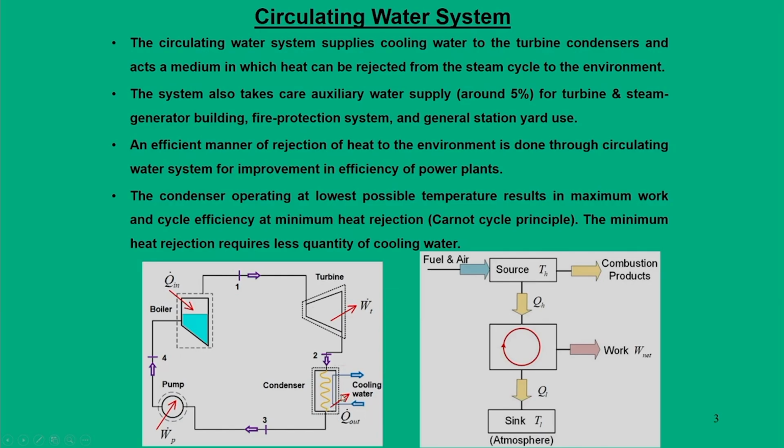Heat rejection is a must, because based on the Carnot cycle concepts, this is a heat engine which operates in a cycle, and this heat engine cycle is nothing but the thermal circuit of the steam power system, in which one way of heat rejection is the heat rejection in the condenser. Now, where does this rejected heat go? It goes out to the cooling water.